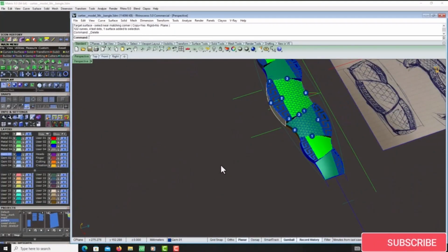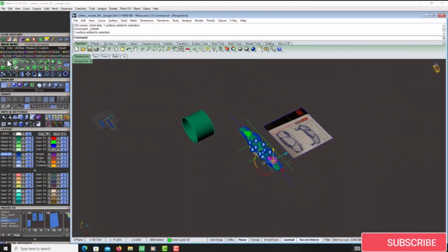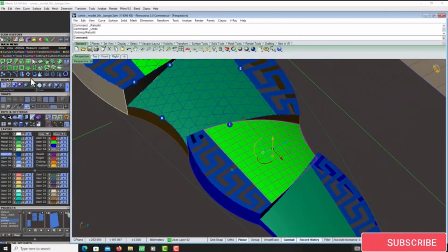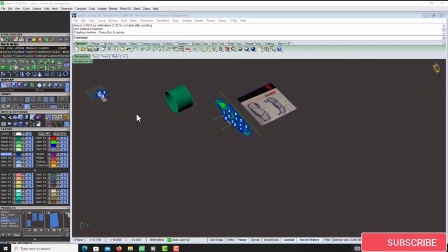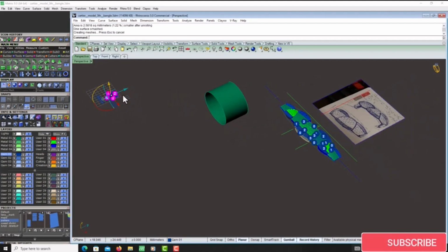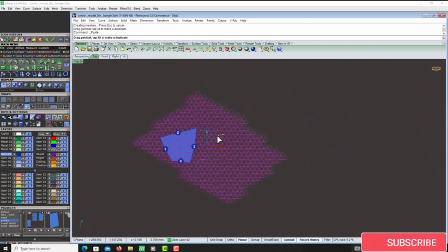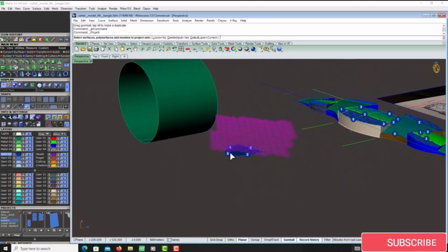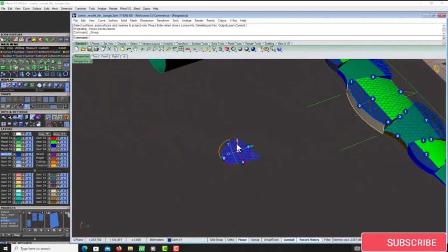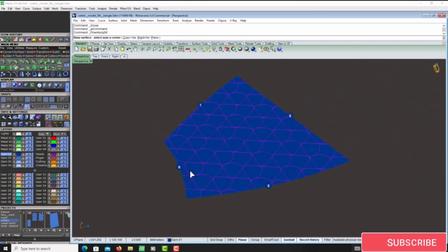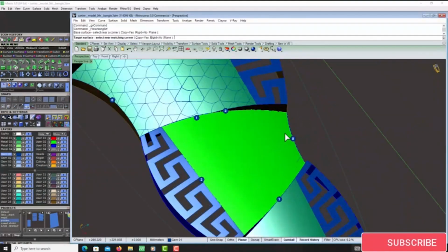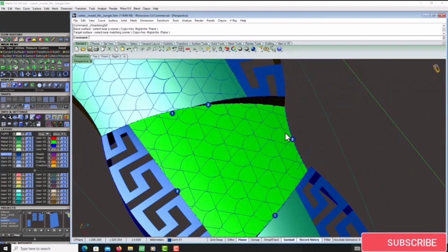I explain this again. You have a green surface on your bangle in a base. Okay, you first shrink your surface, then smash your surface. Okay, smash it, yeah, and move it to a better place. Okay, and then you move your pattern on top of the smashed surface, and then project your pattern, going to curves and click on a project icon, projecting on your smashed surface.